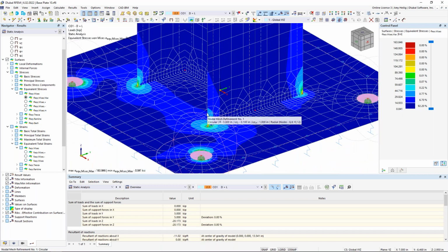You know, these maybe could be attributed more to a singularity. But notice that the stress value here at these high peak points is 163 KSI. And there's something I'd like to discuss a bit further that's really important when we're viewing our results here on these very small scales for these steel type connections, for example.